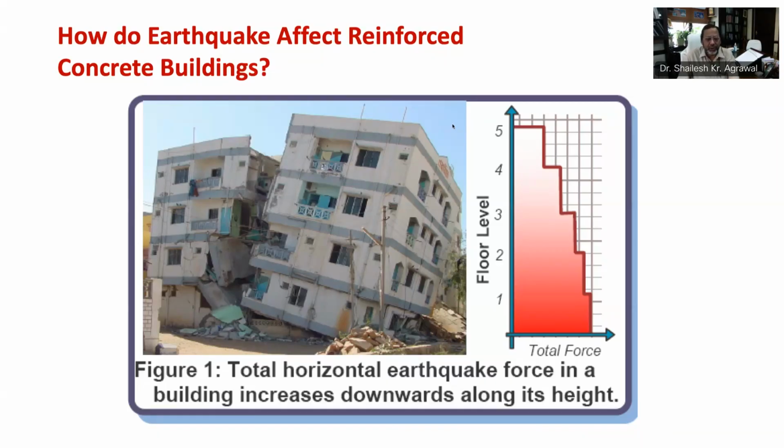across the globe. A typical RCC building is made of horizontal members, namely beams and slabs, and vertical members, namely columns and walls. And these are supported by foundations that rest on ground. The system comprising of RCC columns and connecting beams is called reinforced cement concrete frame or RCC frame. The RCC frame participates in resisting earthquake forces.